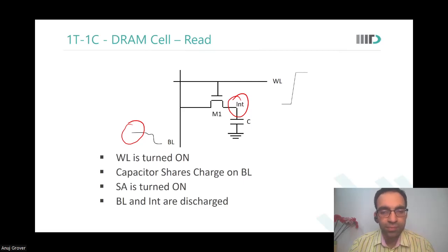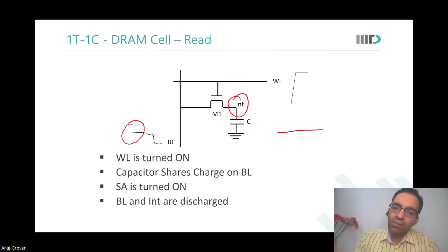So this is not the point. Suppose you pre-charge the bitline to VDD and then do a read operation. The internal node had already, due to leakage or whatever, reached a level of VDD minus 200 millivolts. In reality, because it was storing a 1, I would not expect my bitline to fall anything.